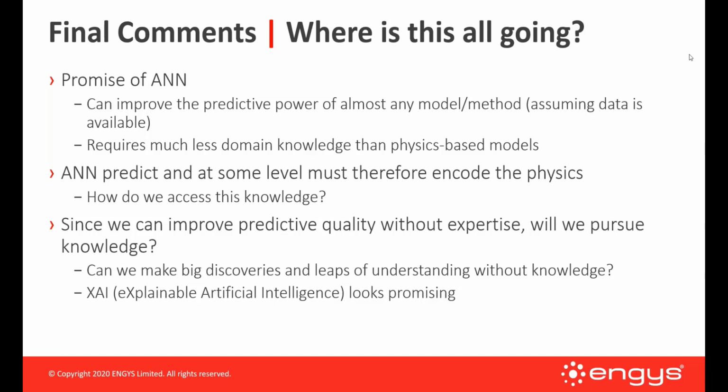For the 3D case, on our available GPUs, we hit limits with 128 cubed. So there are some severe sampling size restrictions for GPU usage. Now there are bigger GPUs coming along, and we did not use the GPU with the biggest memory availability on the market currently. So I think we could quite easily fit the 128 into a top of the range Tesla card. Ideally, we would like to use 256. That gives us a resolution of some features that are important to the aerodynamics, specifically grill shutters and underhood flows. We're not sure whether that'll be feasible.